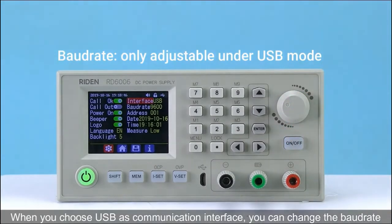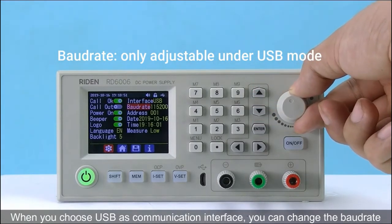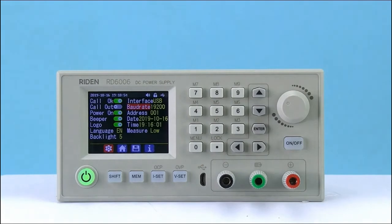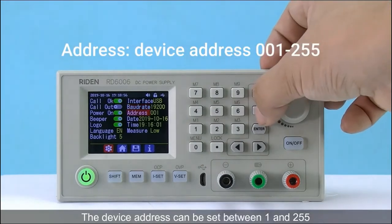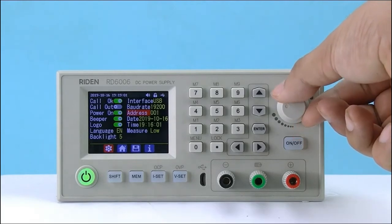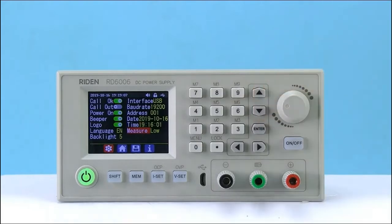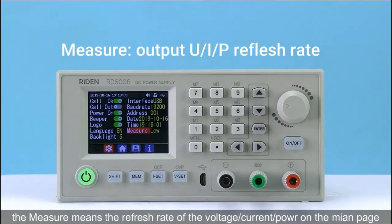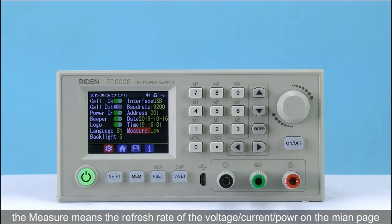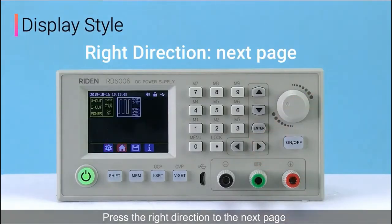When you choose USB as communication interface, you can change the baud rate. The device address can be set between 1 and 255. Here you can set the date and time. The measure means the refresh rate of the voltage, current, power on the main page. Press the right direction to the next page.